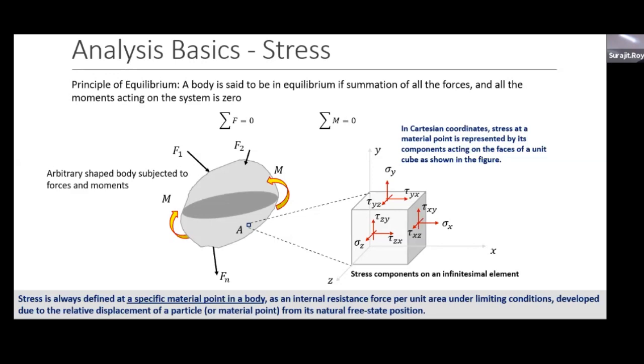So when you say heat treatment, is it surface heat treatment, or what are you talking about? Are you talking about the heat treatment of the whole part, or the surface heat treatment? Of the specific part. Okay, so that is true. You can do the heat treatment and you can relieve some of the stresses or residual stresses. But the cons for that is that the heat treatment is adding cost to the process altogether.